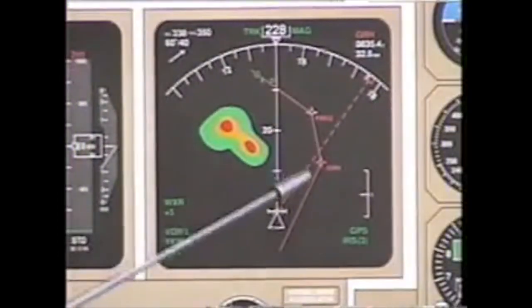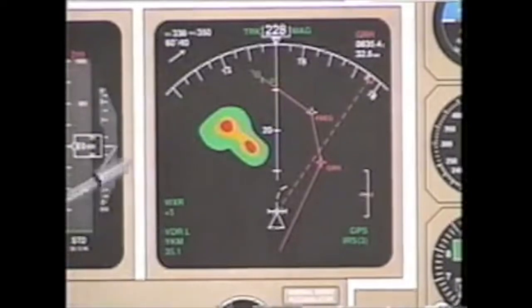Moving to the right of the PFD, our nav display or ND. Upper left-hand corner of the nav display, we always have our current ground speed displayed. Remember, there's 3 taxi speeds as we go out or taxi in that we need to respect. Ground speed, upper left-hand corner, recommended straight ahead speed is 25 knots. If you're making a turn less than 45 degrees, the recommended speed is 15 knots. And if the turn is greater than 45 degrees, 10 knots.